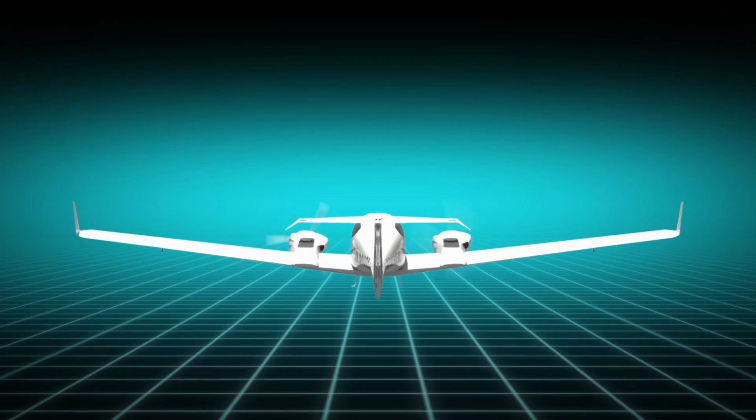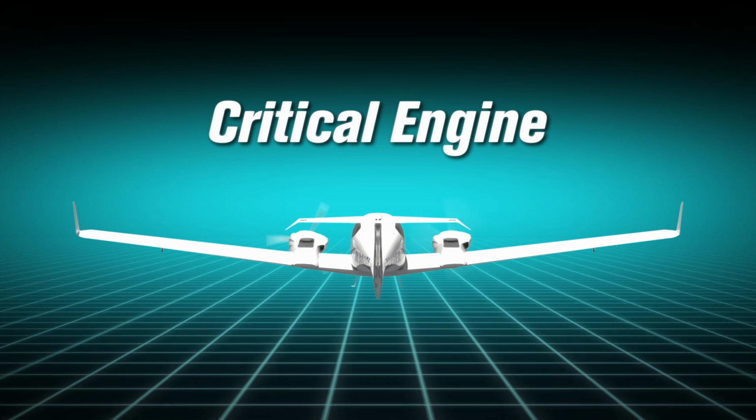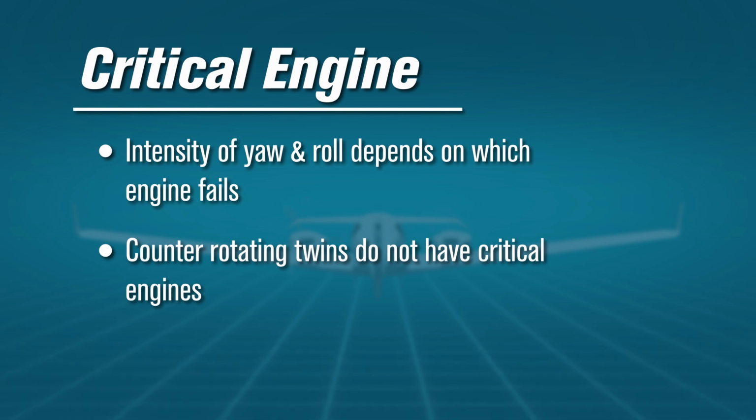Critical engine. Another important concept to learn is the critical engine. This term is used frequently when discussing one-engine inoperative conditions in a multi-engine airplane. In certain multi-engine airplanes, the intensity of yaw and roll produced when a particular engine fails might be different than when the opposite engine fails. This is especially true in multi-engines with conventional rotating propellers. In multi-engines with counter-rotating propellers, the aircraft reacts the same regardless of which engine has failed.